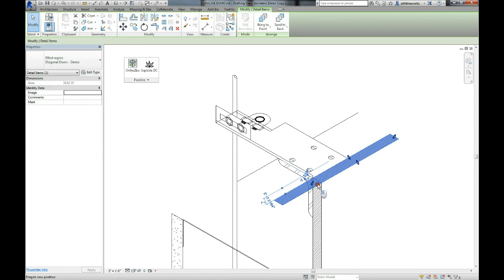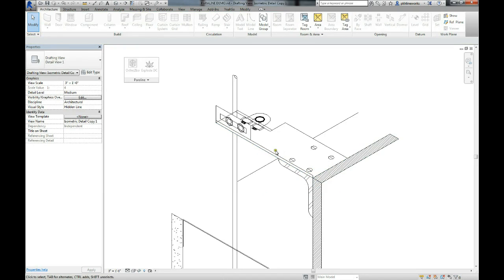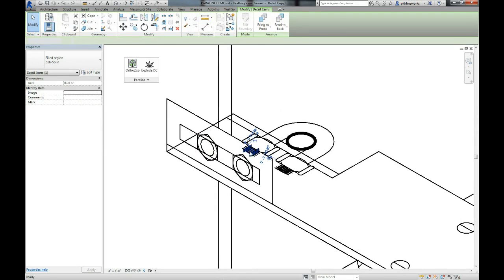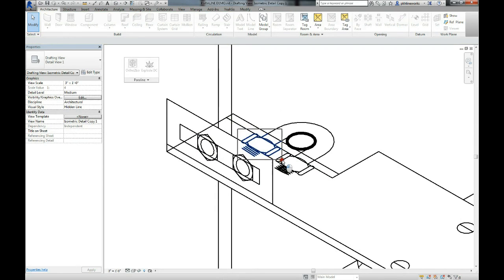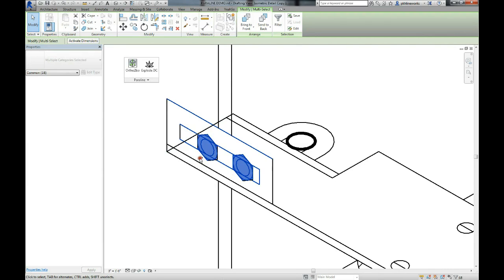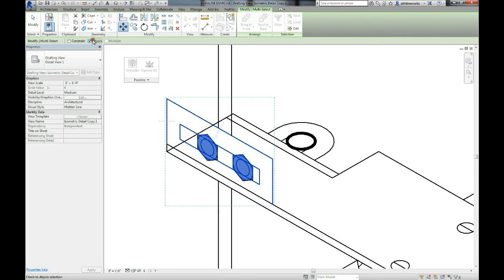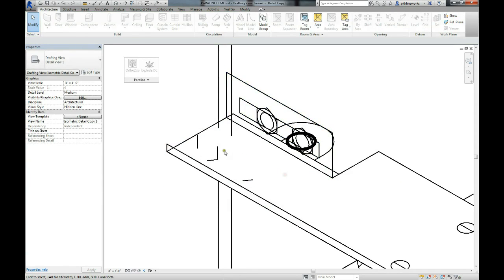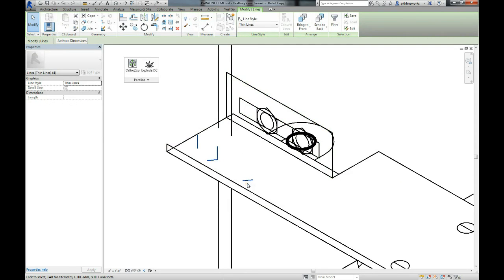First we'll just cut this back to make a nice corner on here. The bolt assemblies, we don't need the plan view of the bolt assemblies, we actually want to use the elevations, so we'll just take these out. Of course we want to align this up because this is a bent up portion of this assembly. You'll find this join helps quite a bit here, and this will actually appear back here. Should probably take these as well.